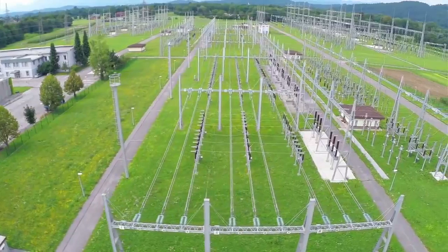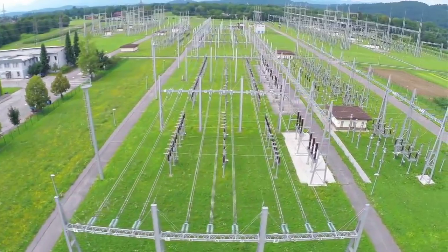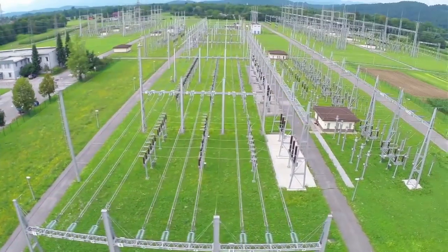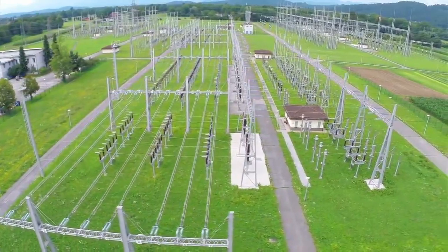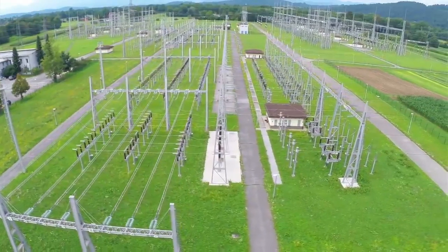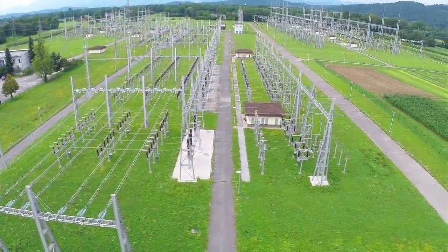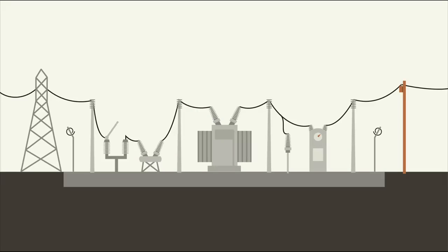The connections to these various devices are called buses, often rigid overhead conductors that run along the entire substation. The arrangement of the bus is a critical part of the design of any substation because it can have a major impact on the overall reliability. Like all equipment, substations occasionally have malfunctions or things that simply require regular maintenance. To avoid shutting down the entire substation, we need switches that can isolate equipment, transfer load, and control the flow of electricity along the bus.